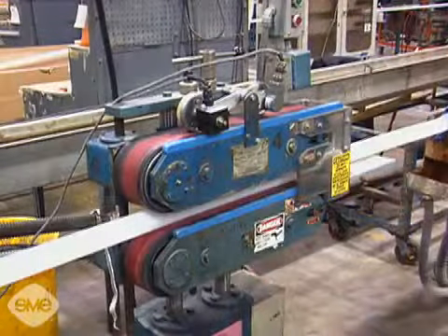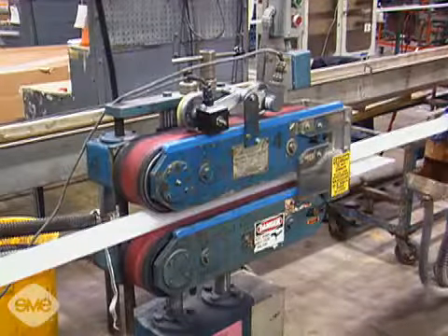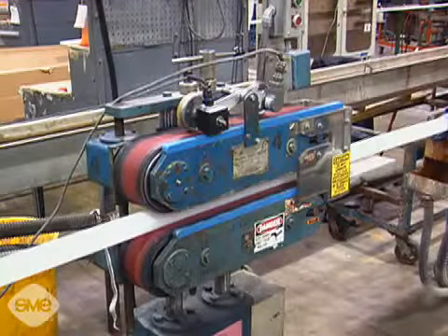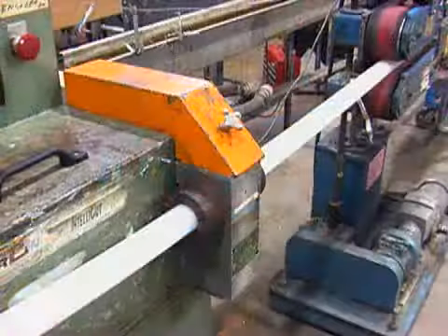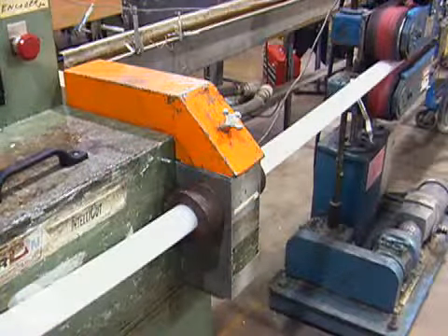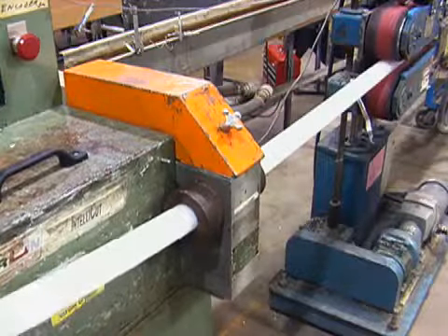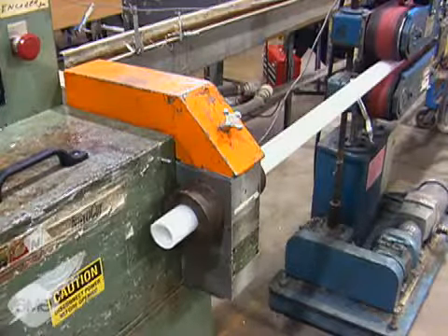At the end of the cooling tank, haul-off rolls pull the profile away from the die at a uniform controlled speed. As the profile is pulled through the haul-off rolls, a cutter shears it to the required length for further processing.